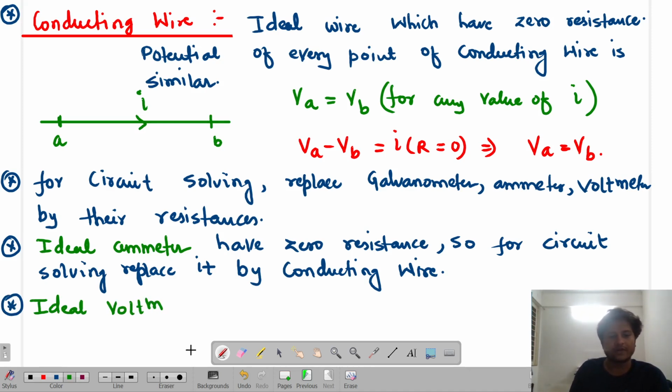Now, if I want to find any kind of potential, we use a voltmeter, isn't it? And basically, you will see that voltmeters are connected in what way? Parallel way, such that we find the potential drop. And if it is connected in parallel, that means the net current through the voltmeter should always be zero, isn't it? No current should go through there, such that the voltmeter will have zero potential drop. So any voltmeter, if the current needs to be zero, should have infinite resistance.